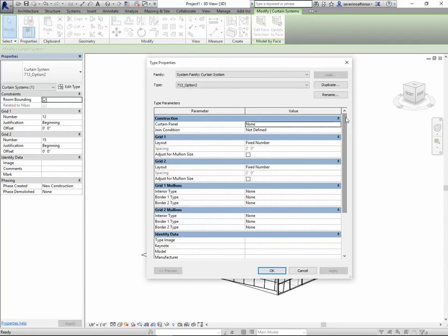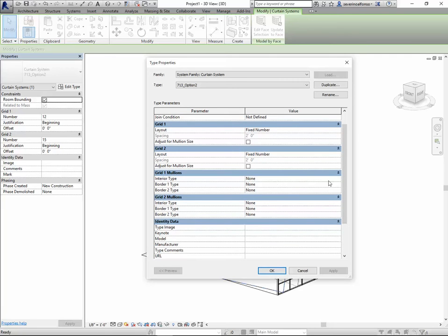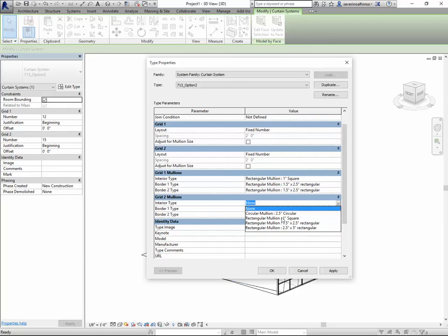What other things can we change in the current grid? You can just say current panel and it says none right now. You can say empty panel if you only want the mullions. That will just not have the glass there. You might want to have a division of mullions only, and then you can just start adding these elements. Let's say we want to have as we had before. It's going to take time, so many mullions there.